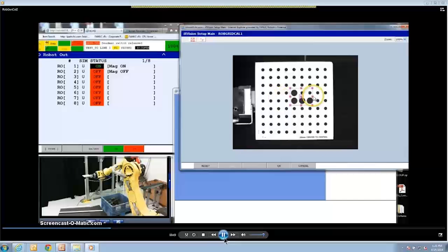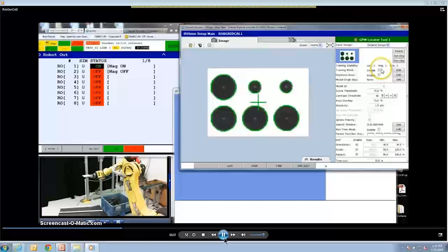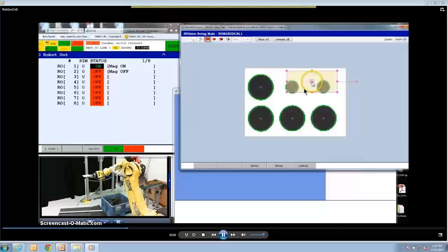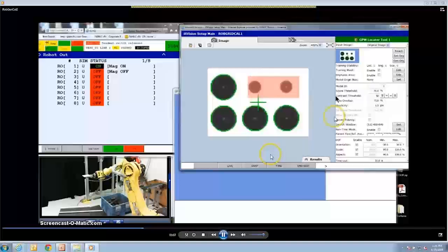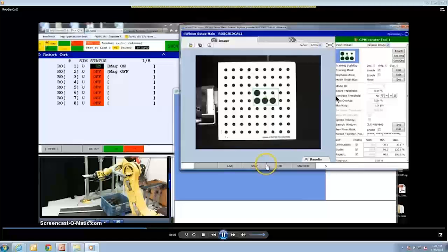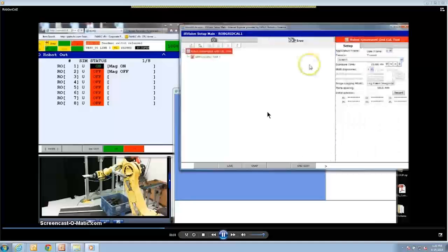Make it a little bigger there. Just cutting off that one circle. Not really a big deal, but I don't know. Just usually I like to just use the L. I'm going to get rid of these two dots. Could leave those in, really. Doesn't really matter. So there we go. I'm going to change my overlap down to 5%. That'll prevent it from finding it flipped with a ghost circle, which sometimes it'll do.